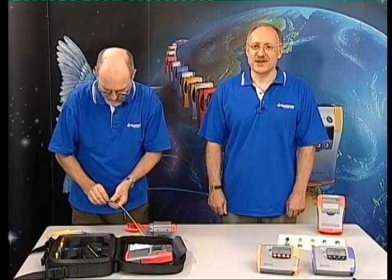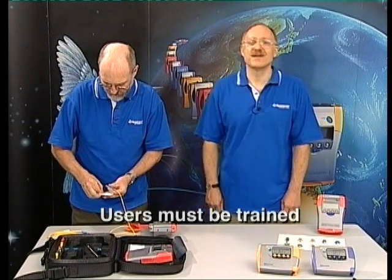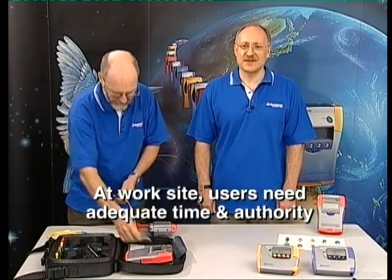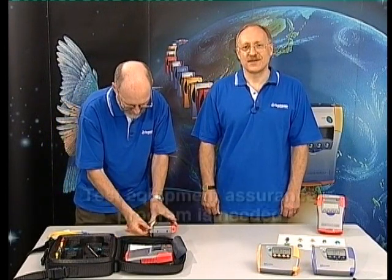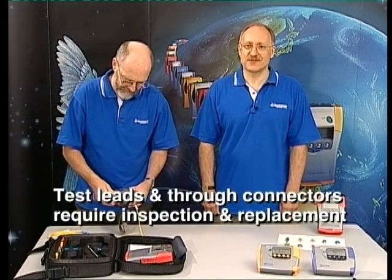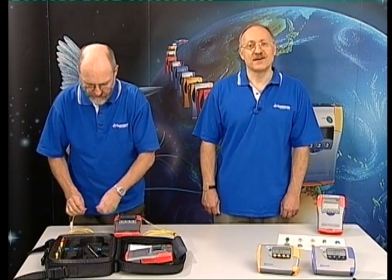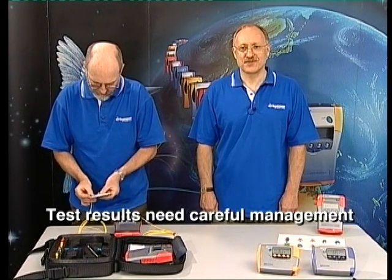Optical loss testing is performed at all phases from R&D through to manufacturing, system installation, and maintenance. So there are many different requirements for test accuracy, speed, and flexibility. There are various general management issues to consider. Users must be trained. At the worksite, users need adequate time and authority. A test equipment assurance program is needed. Test leads and through connects require a program of inspection and replacement, since they get damaged or worn. Test results need careful management, which is time-consuming.